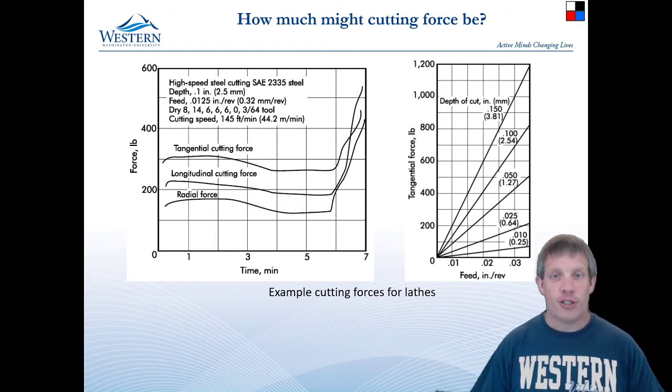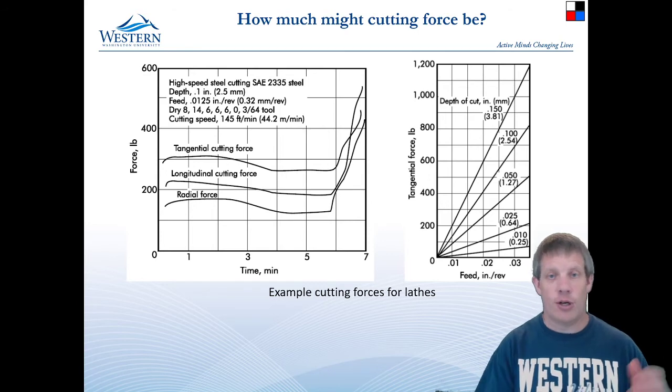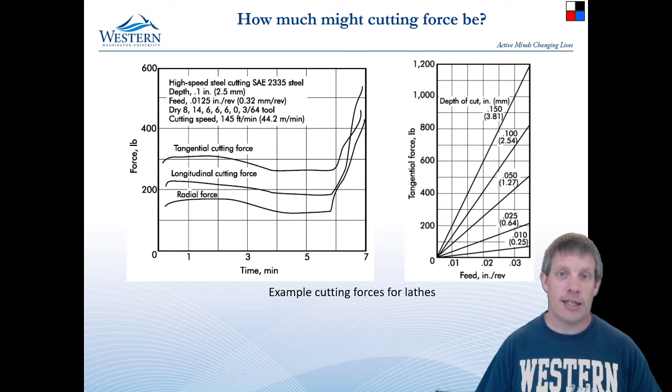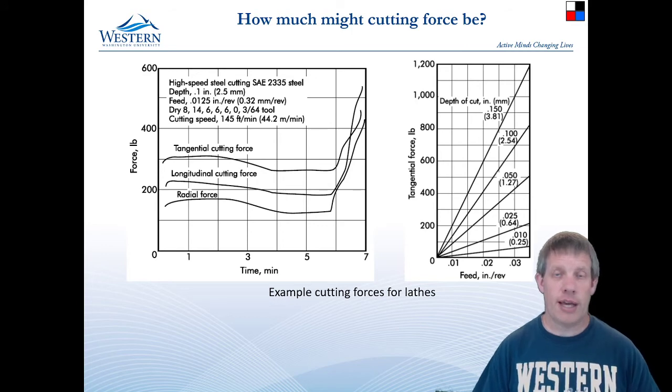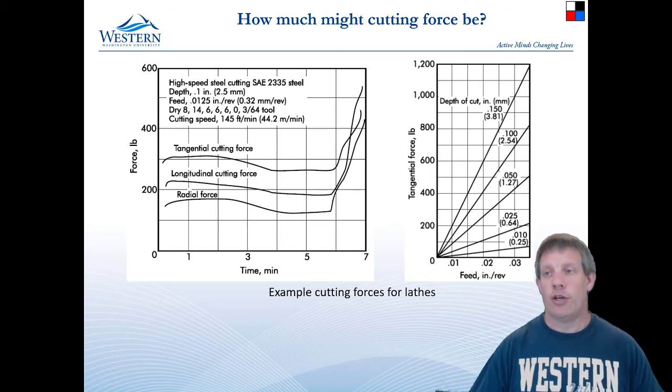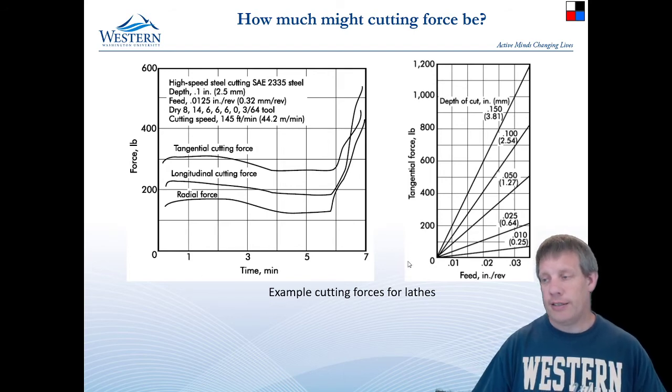the tooling forces are going to go way, way up, and you cannot allow the part to come hurtling out of the fixture just because they did that, because somebody could get killed, or you can cause a lot of damage to machinery. And so we always need to apply a safety factor in the end.